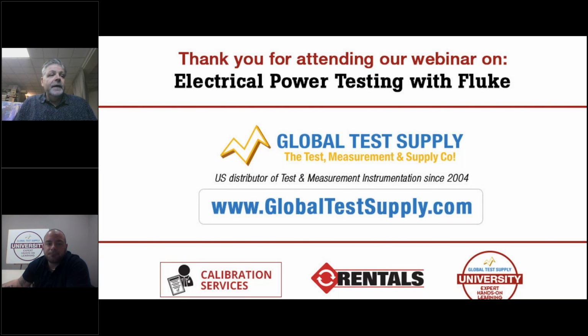That's a good question. Calibration frequency, the way I like to answer this question is it's actually more user dependent, and maybe potentially your customer dependent. So let's just take it away from power quality and have a general discussion about calibration. Calibration is a test to a primary standard. You provide traceability saying that this standard is tested to that, and it cascades up the chain of reliability in terms of how accurate the measurement is, if it's within standards or not.